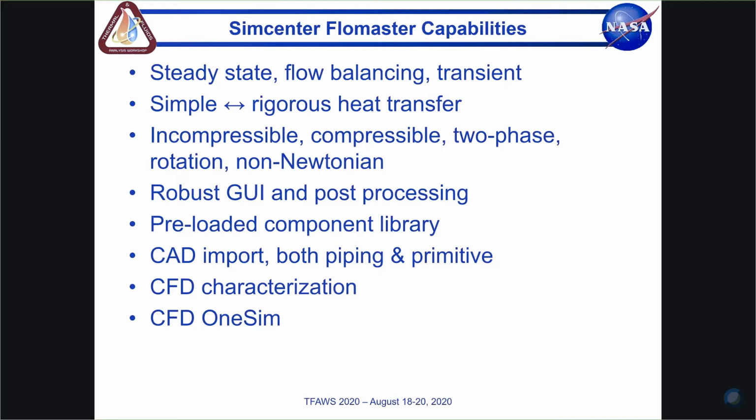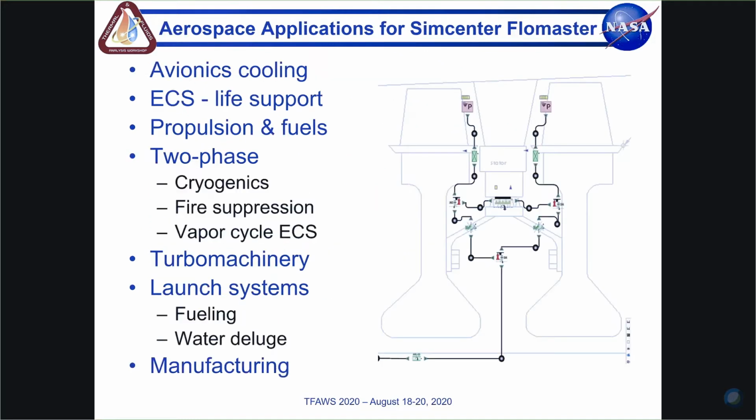Along with that, we leverage 3D CFD to characterize parts. So we have automated technologies to incorporate characterized data from 3D CFD, bring that in and make 1D components out of that characterization study. But we also can do co-simulation with 3D tools. And in particular, with SimCenter Flow ESD, we can do something called OneSim, which is a closely coupled co-simulation where actually all of the analysis happens within one of the solvers. It happens inside the Flow ESD solver. We'll take a look at that as well.